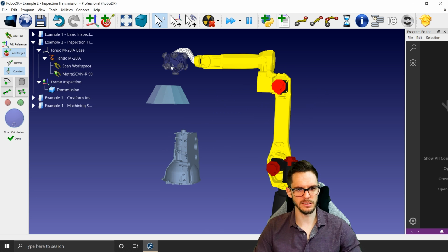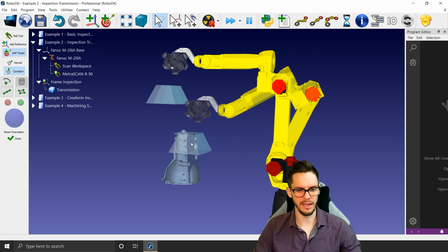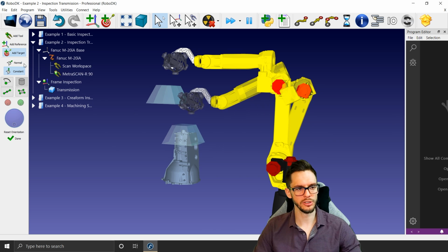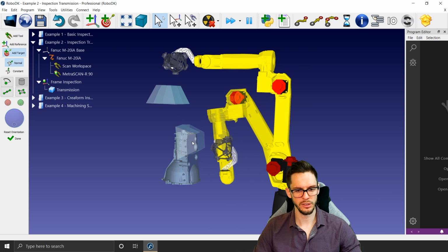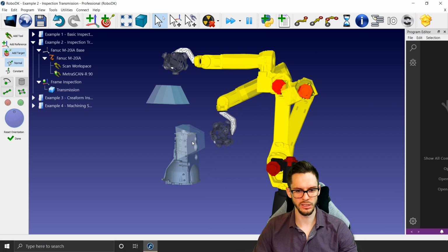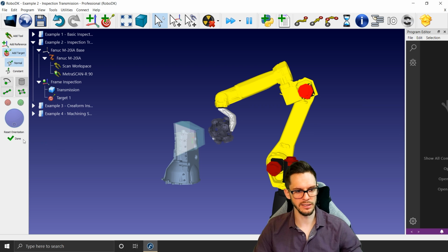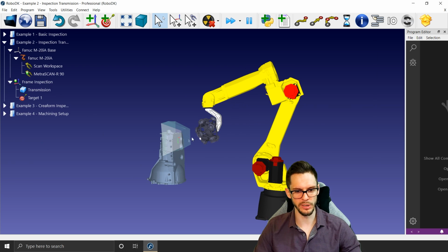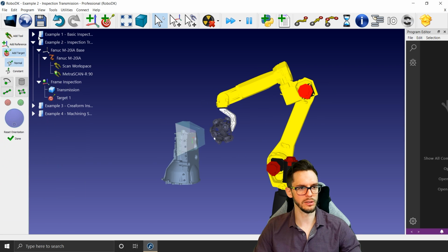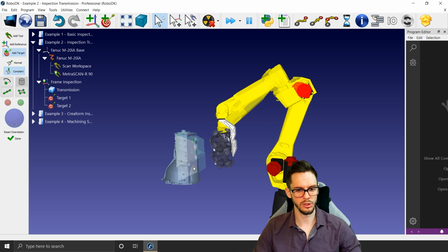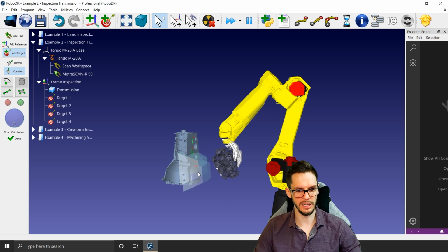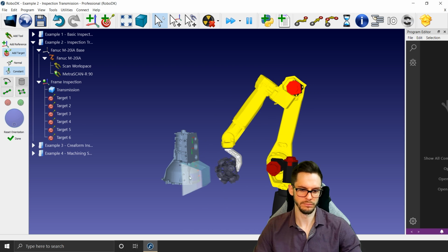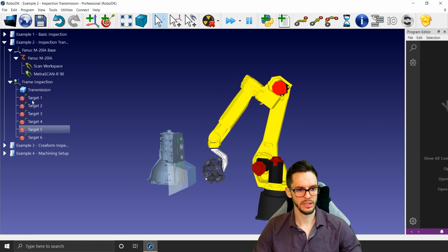Right now, as you can see, it's mimicking the orientation we have right now, so it's not necessarily what we want. So if you want just a small trick on this one, you just go with the normal for the first one, you adjust the rotation like that, you create your first target, you escape from this feature, this will create your first position, and you know the robot is now at this place here, and you can go teach target on surface again. Now you use the constant method, you create your targets, and then you have the result, the expected result.